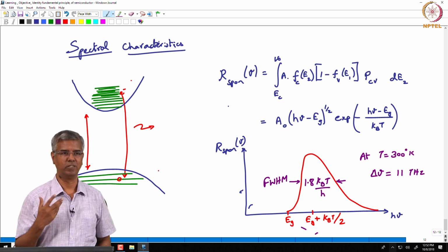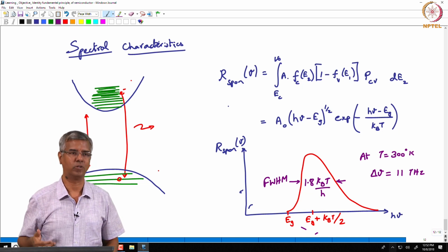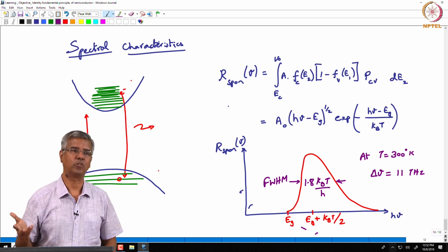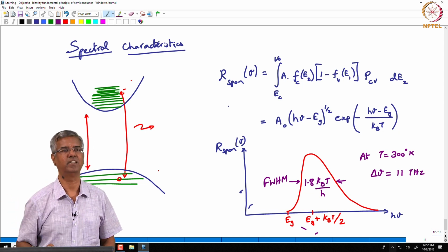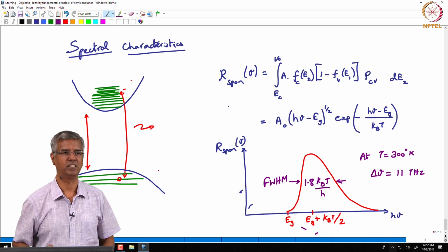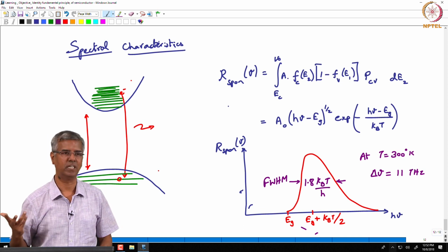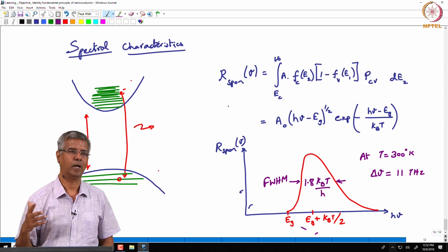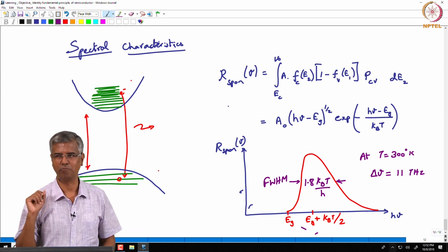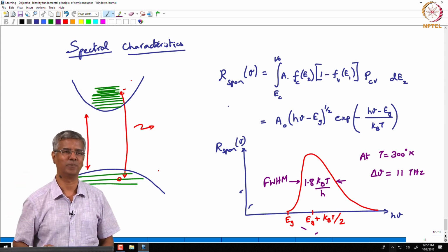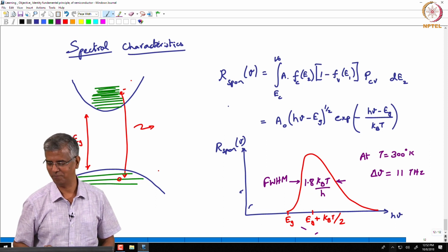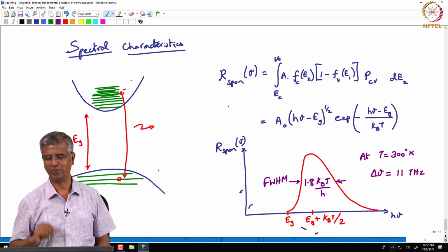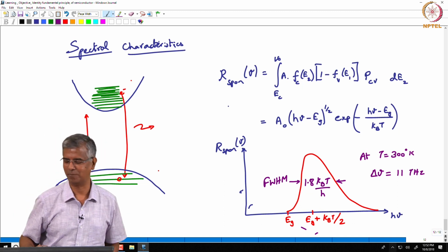So yes, there is a conversion efficiency involved. There are some photons that could be scattered and not really going through that conversion. I believe the conversion efficiency is greater than 50%, but depending upon the thickness of the phosphor coating, you may or may not absorb all the UV radiation. So I'm fairly sure I'm going to see a UV component coming out of this, and I'm actually curious, as you are, to find out how much of that UV component is coming through.